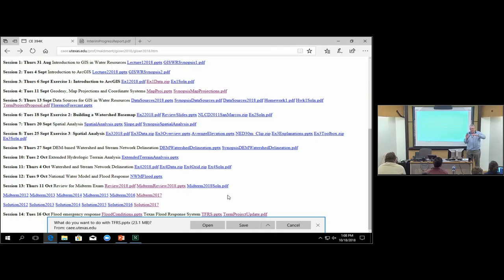One of the things that we found is that the USGS has a stage height at each gauge, but sometimes there can be almost no flow and the stage height is 10 feet. That's because they put the datum of the stage well below the bed of the river in case the bed of the river gets eroded. But it means that calculating water levels and comparing them to observed stage heights can be just gobbledygook. So what we're doing is adjusting this so that the stage heights and water levels are consistent with each other at each gauge.